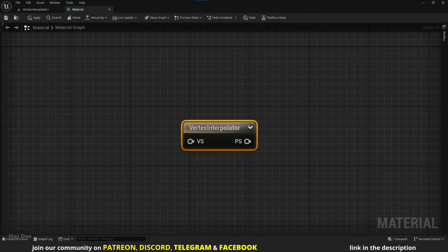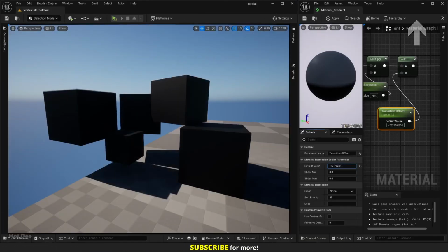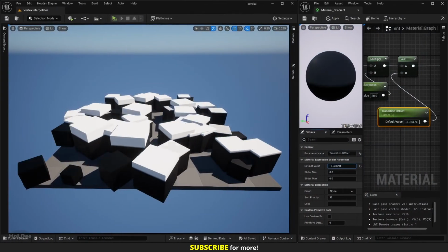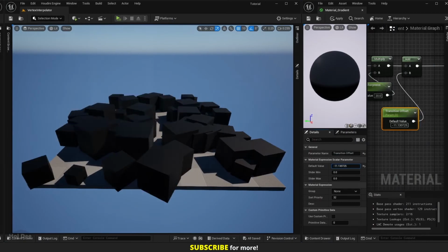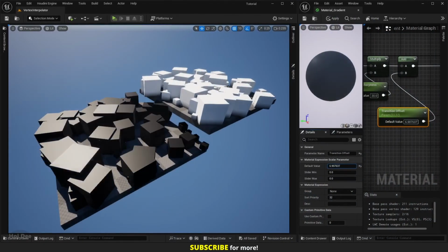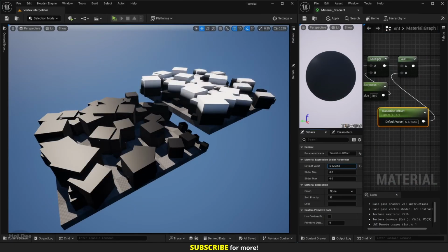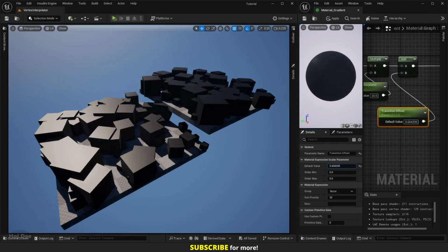We can use it with instanced objects. I've created this material to add world aligned gradient on meshes. When used with static meshes, it works just fine. But when we use it with meshes that are scattered with the foliage tool, it recognizes the collection as one object. We can see it better in places like this where there's a height difference. These are scattered with the foliage tool, and the whole collection of instances are being treated as one object. We can see it in the way the gradient is placed on them.